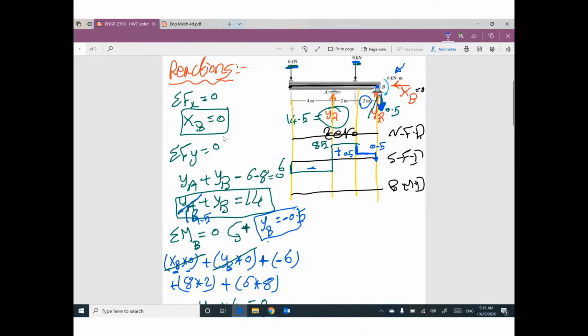To draw bending moment, I'm gonna start from left. If you have a free end or hinge or roller, in other words, we don't have any concentrated moment, we don't have something like this, so your moment at the beginning will be 0. I need to figure out the values here. So M1 is 0. What is the value of M2, M3, M4?